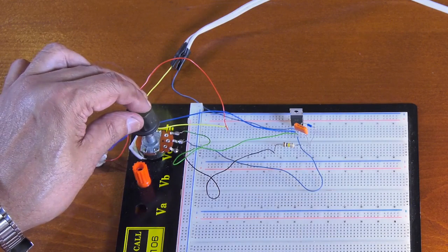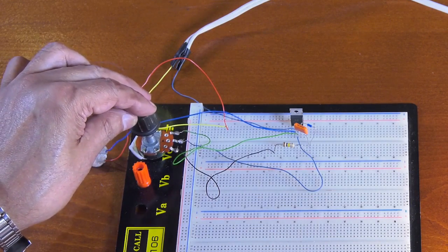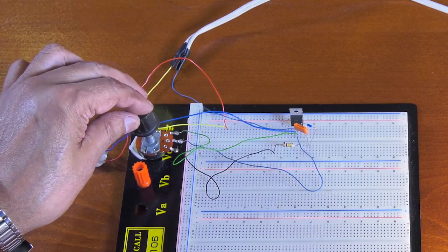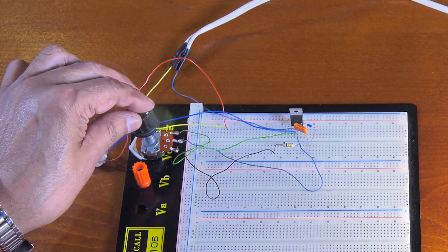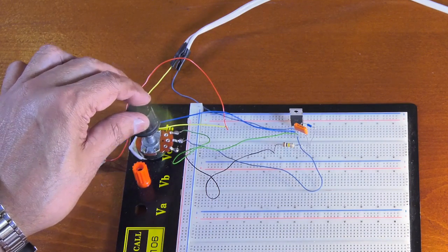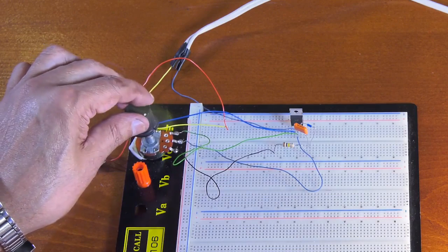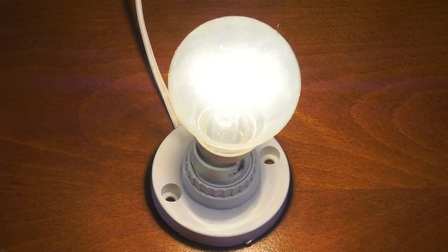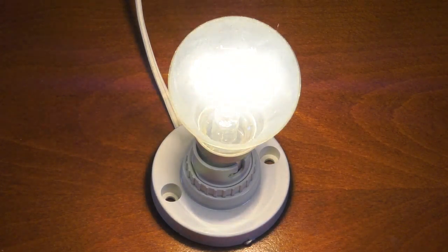You just need a capacitor which is connected to a diac. By the way, a diac must be used to trigger the gate. The triac also has a gate very much like the SCR. The gate is very, very sensitive, so we need something to keep the sensitivity at bay. We normally use a diac which has a breakover voltage of about 40 volts, and that triggers the action of the triac. So in this experiment, in this project, we have used the triac to demonstrate phase control.